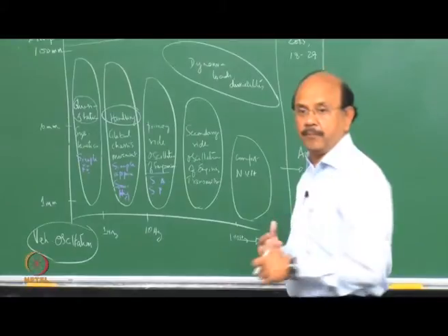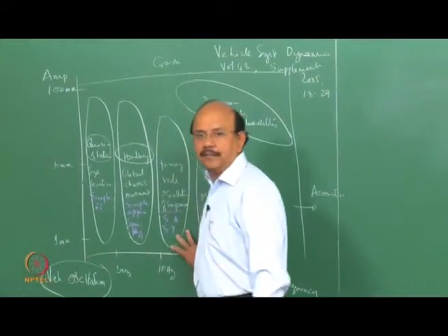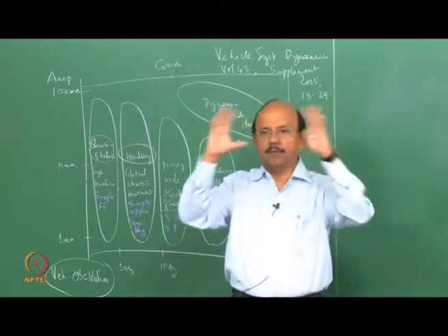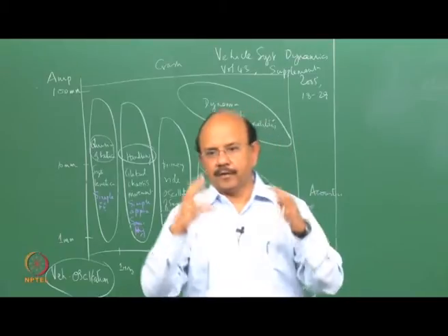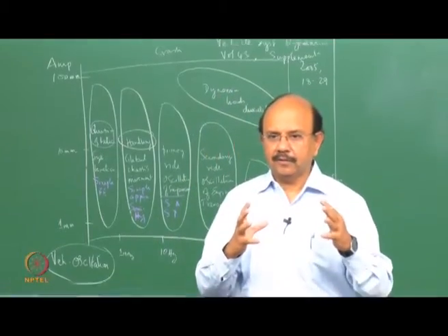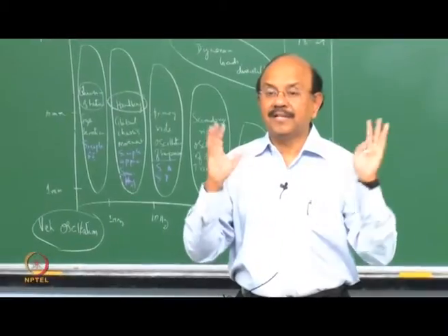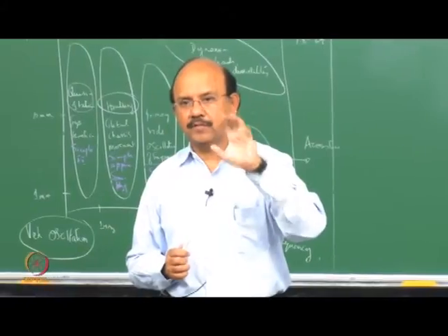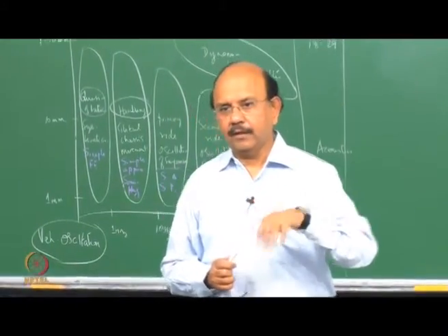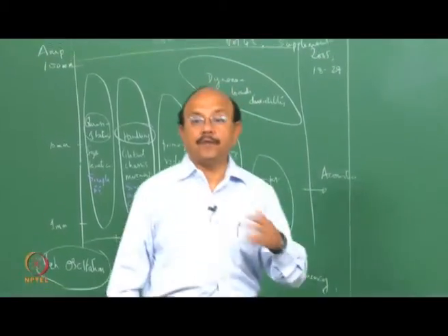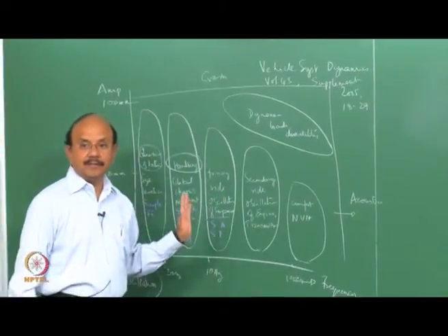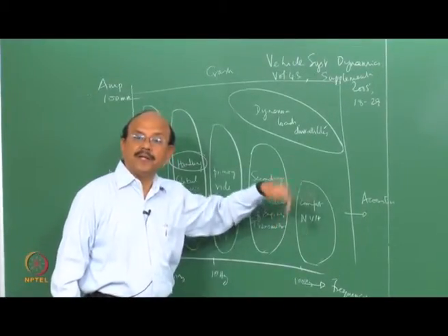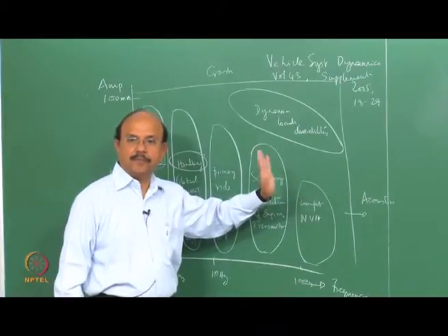For example, when you are looking at the primary ride, you can treat this whole body as a rigid body, and we are going to look at it as a rigid body at those frequencies. So in other words, the frequency is dominated by the spring-dashpot system of the suspension. When I go to higher frequencies, there are contributions at higher frequencies, and that may be due to bending of the chassis frame.